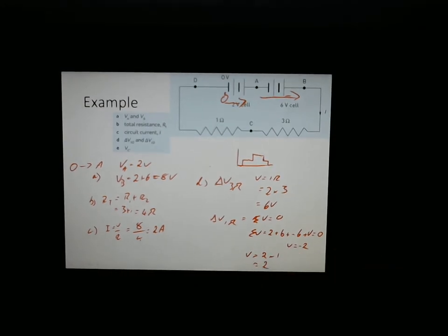Now, note, that's a negative and that's a positive, so which is right? The negative tells me that the voltage is being used up. So when you're using Kirchhoff's law, you've just got to be really careful about your signage. Batteries, positive things that give us voltage, have to have a positive, while things that use up voltage must have a negative. And when you get really complicated circuits and you've got batteries facing in the wrong direction and you don't know what direction things are going, you just pick one and you make sure you stick to it and go, well, I'm going to say it's that way is positive, so some things might end up being negative or some things might end up being positive.